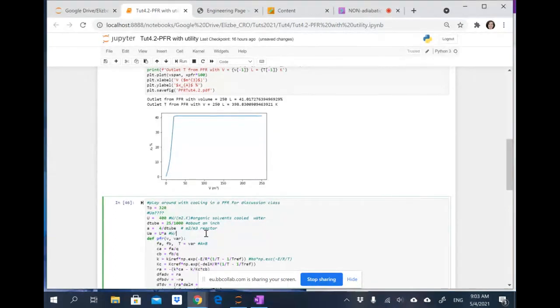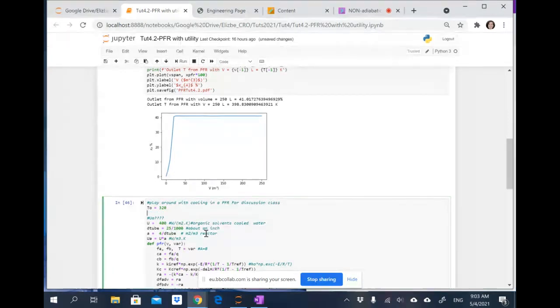And what is the volume parameter that I'm using in my model currently? I have the volume of my reactor. Let's just put it over here so we can use it. The volume of my reactor, I'm going to choose as a basis 100 liter reactor for today. I've got that in liters. Okay, so now I must fix something here because I want this to be in units of watts per liter Kelvin. So I must change that.